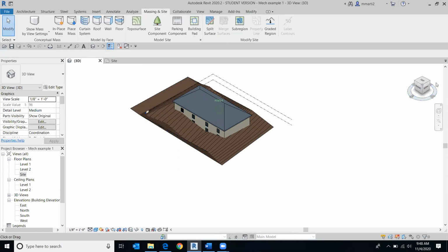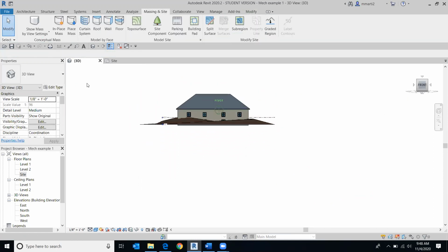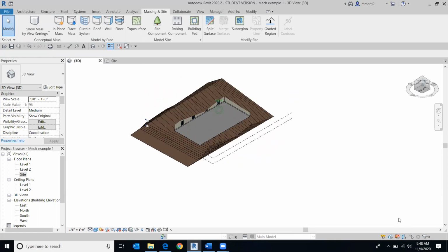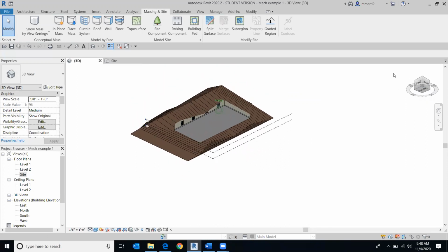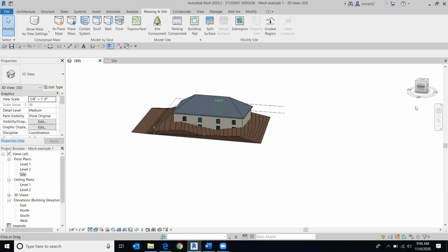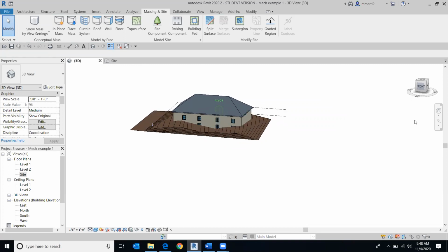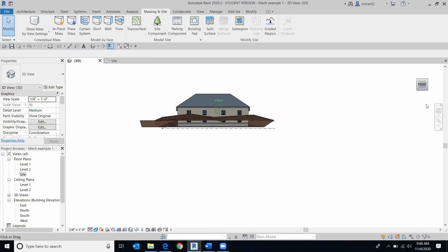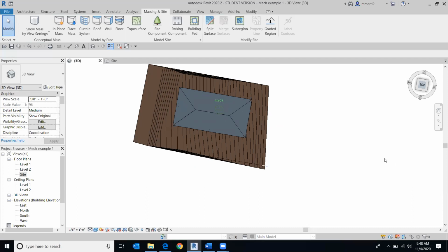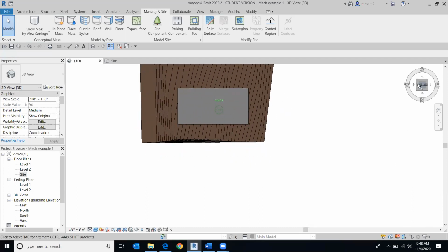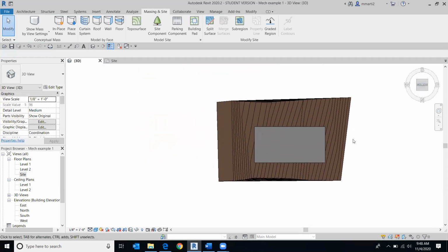So another thing that you want to think about when you're adding these different elevations in your site is that now we have to cut out that site section from the interior of the building like we did with the other sites before. And even when we do that, we're still going to have all this ground that's up high over our building and cutting into that. So we need to actually have the building itself on a level foundation. So how do we do that? Let's do that next.